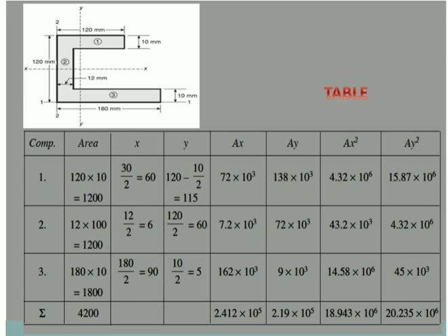Similarly obtain y bar. Here y bar can be calculated as 100 by 2 plus 10, because if you take the element height as 100, y bar will be 100 by 2 plus 10. Or you can take the total height and by 2, then the plus 10 will not come. Instead of 120 by 2, you can also go ahead with the height of the second element, 100. I have put this purposefully because you have to think at these points.